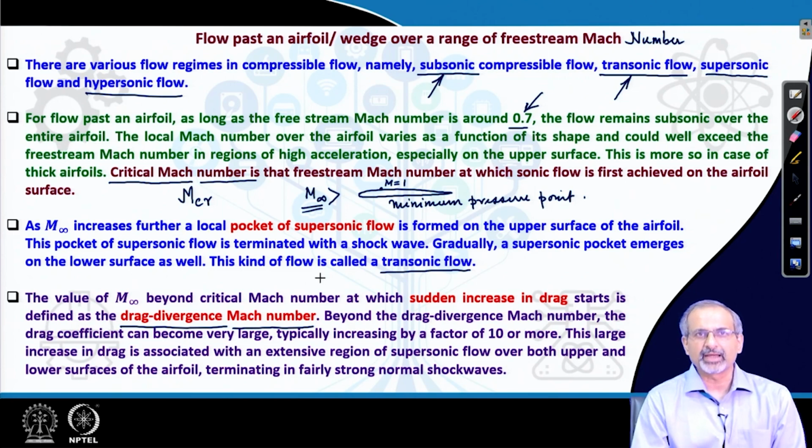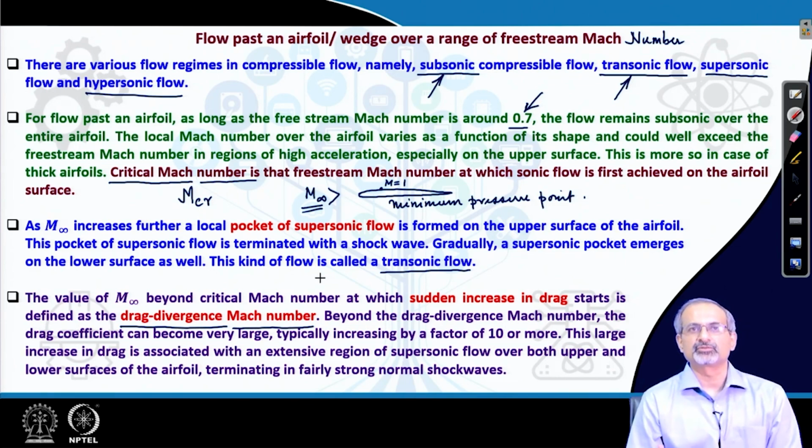So, this drag is usually associated with both the wave drag aspect as well as additional flow separation, which are caused due to the formation of the normal shock waves at the end of those pockets of supersonic flow.